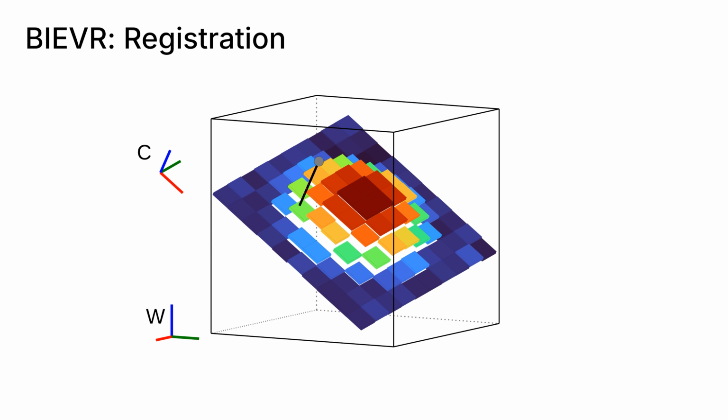The BIEVR representation can directly be used for scan-to-map registration. We minimize the difference between each input point's height above the image plane and the stored pixel value. The resulting Jacobians combine a normal direction term similar to point-to-plane ICP, with 2 additional gradient directions from the height image, which provide constraints in directions that are unobservable under a classical point-to-plane optimization.